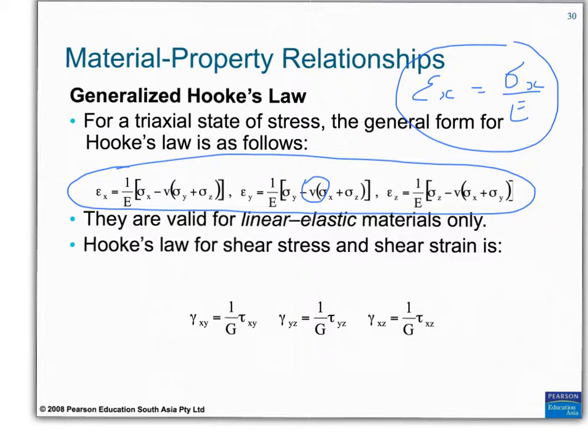Okay, so using those equations, we can then take our measured strains, convert them into strains in X, Y, Z directions, and the shear strains associated, and then we can use the generalized Hooke's law to find our stresses.